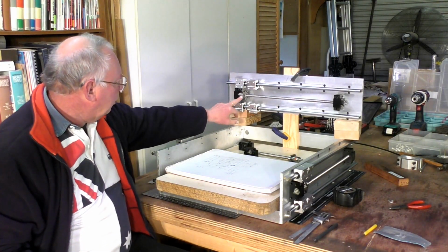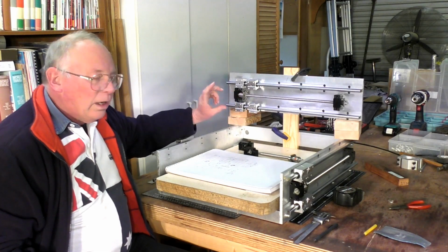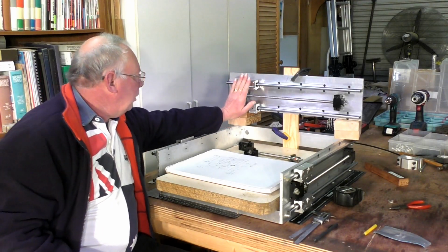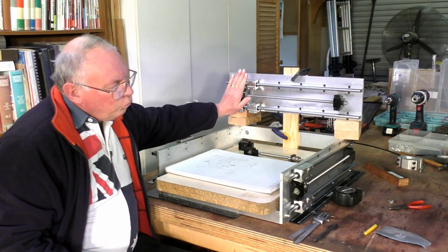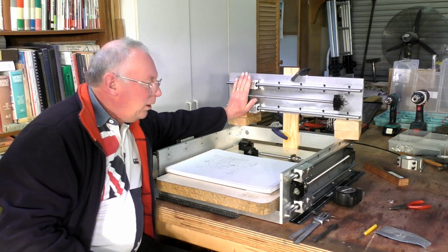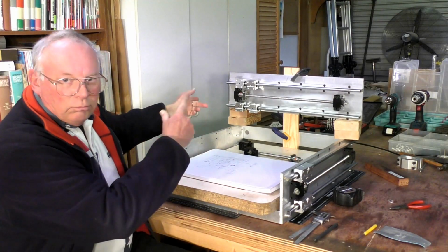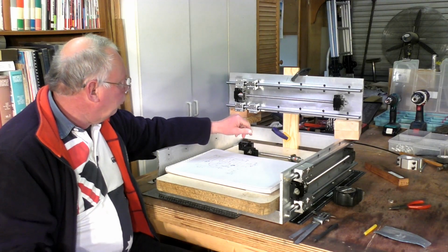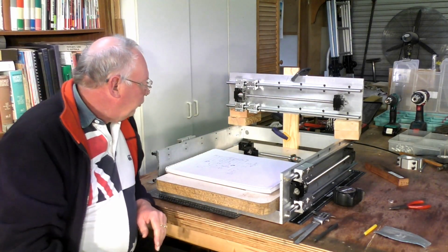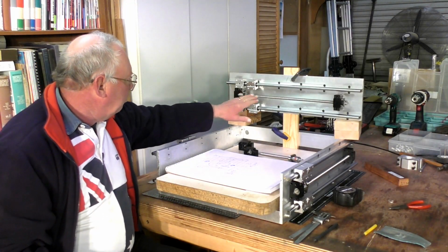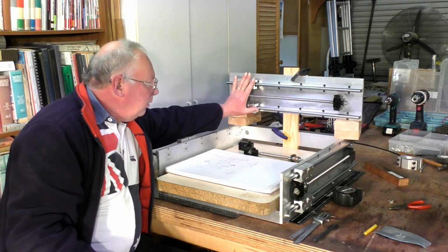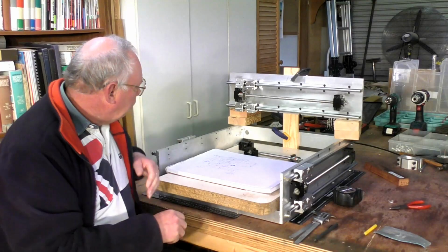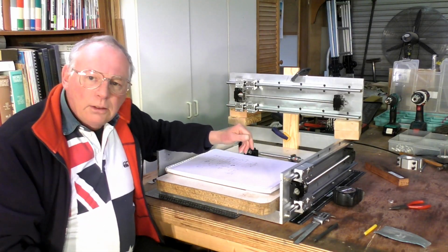In other words, the ball nut's going to go here and this aluminium block is going to go on the ball nut to connect it to the 12mm thick aluminium plate that's going to go on here, and indeed all the axes, because I need 4 altogether to be able to operate the axes. So it's the connection between the ball screw and nut and the guides, okay? And I'm going to show you how to do that in Carveco Maker.